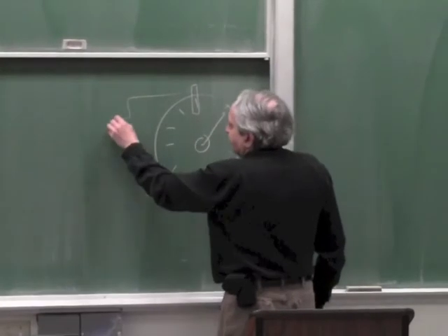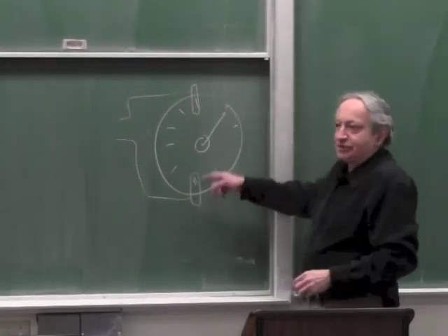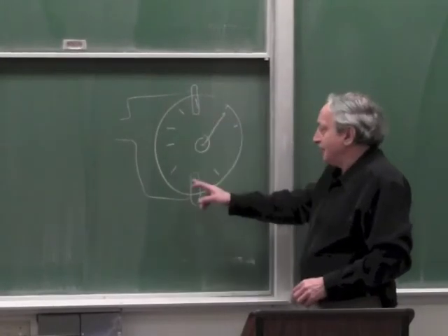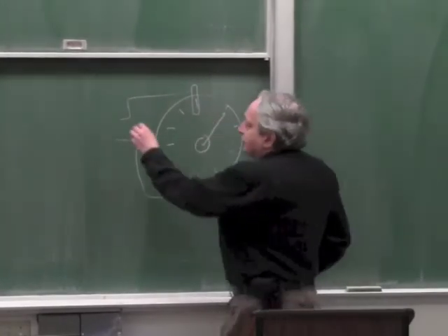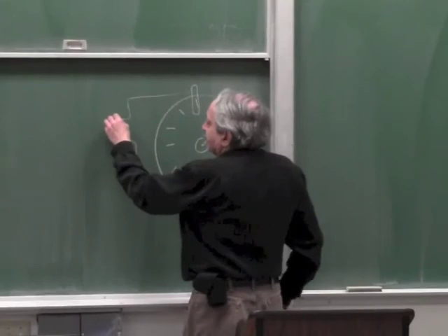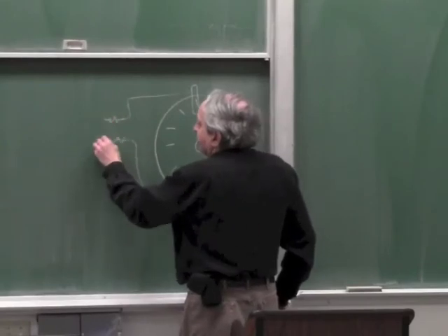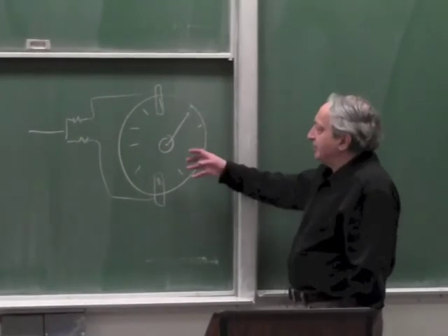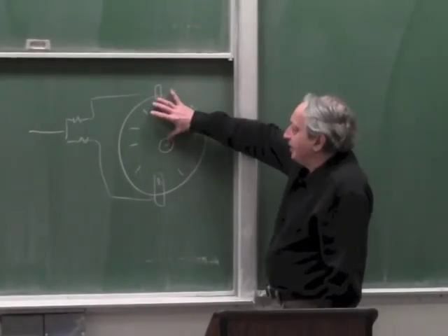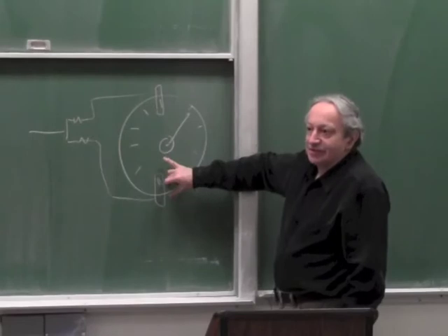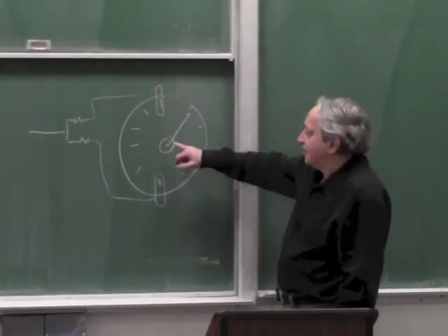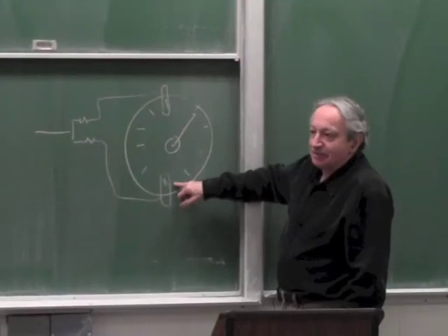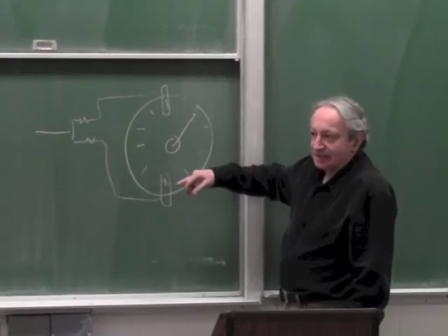Now this is not differential, this is just averaging two stations together. Each reader can be differential if you like to, but this is just averaging two stations together. So it will look like this. And now when the eccentricity makes this maximum radius, this will be minimum radius. So in the example I gave, if this is r plus delta, this is r minus delta, if you add them together, the delta cancels out.